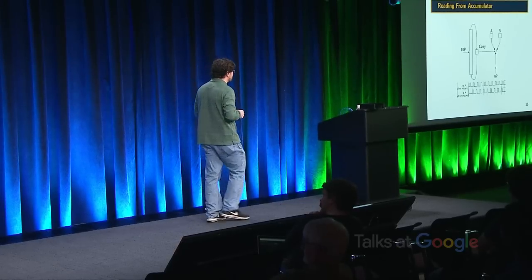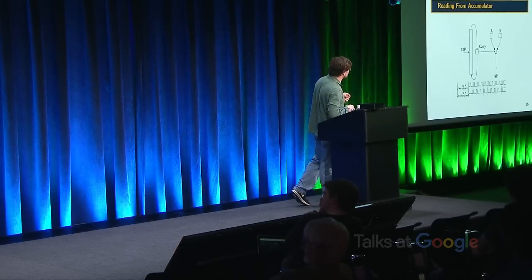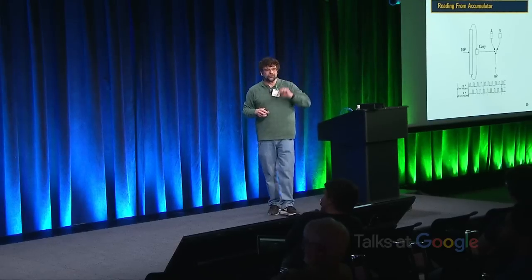So the cleverness is, we'll take the value in that digit and feed 10 pulses into it. That causes the ring counter to go all the way back around to where it started. And in the process of doing so, at some point, it's going to go from 9 to 0. And what happens when we go from 9 to 0? We set a carry.